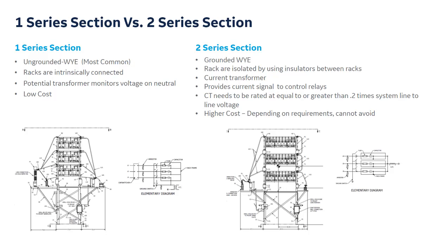So earlier we talked about all the information that I need. If this part can be left open-ended and I have the chance to design an ungrounded Y versus a grounded Y, I'm going to choose the ungrounded Y just to accomplish a cost reduction. But if it's required, we'll go to the two series sections here.